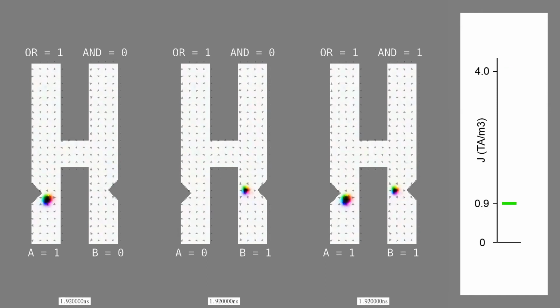This accounts for timing variation, and is also useful for design validation. Here it has been used to guarantee that the skyrmions meet at the central crossing at the same time in order to repel each other. As mentioned earlier, temperature adds variation to the velocity of skyrmions, so the synchronization helps reduce this effect by minimizing the distance before the crossing. The skyrmions cannot pass the crossing until a large pulse of current gives them the energy needed to overcome it.